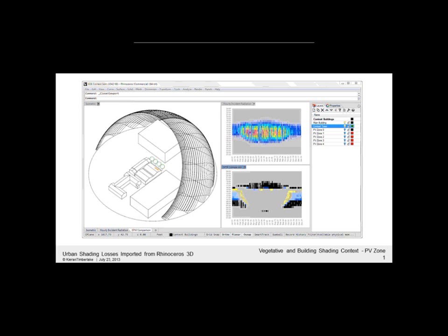Excellent question. If I had 50% of the panels shaded, generally what I would do is, so essentially I cache all of the simulation results so that I can actually graph an animation in Rhino. So if I notice that I have half of the panels in shade and half of them not in shade, I'd ideally want to minimize mismatch. So I have to be cognizant of the given context.